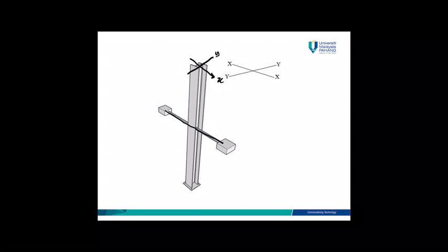And then how to draw the shear force diagram and bending moment diagram, that one is very important. And for column, the important thing is for you to know which axis your column will buckle. So make sure you know how to determine which axis your column will buckle. Okay, I hope that you will get all the fundamental knowledge in this subject so that you can go to a design subject. By that, thank you class.